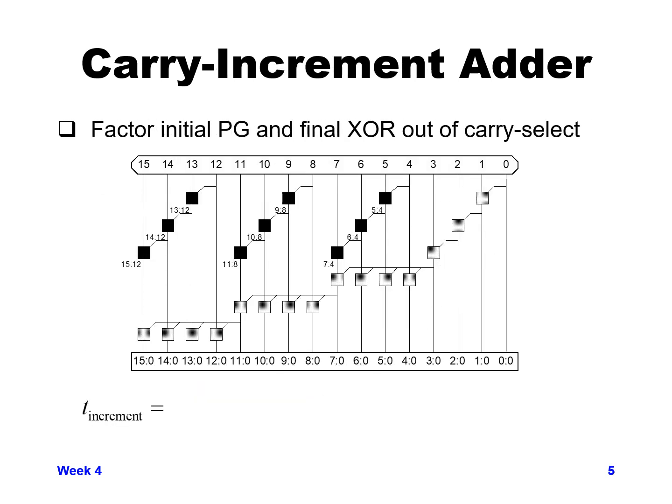The carry select that we talked about in the previous slide was, if you remember, calculating 2 sums for each bit: sum as if carry in was coming in as a 0 and as a 1, and then we were doing an XOR.